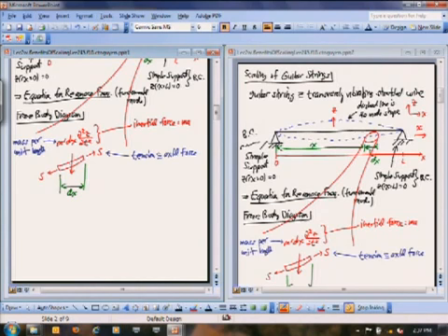And so I'm going to go ahead and, there's my vertical line right here. I'm really looking for this force that's going in that direction. Okay, so I need to know this angle right here, and this angle right there is just going to be given by theta, of course, but theta is about equal to the tangent of theta when theta is very small. So I can express that angle, or at least the tangent of theta, as dz/dx, and then the force component right here becomes S times dz/dx.